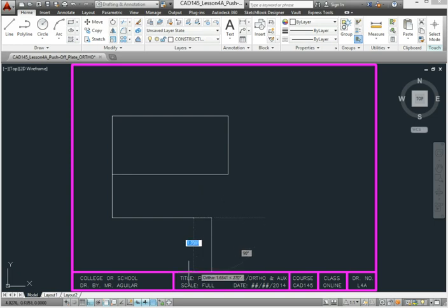This is where ortho will switch to polar tracking. You would move your mouse until the angle reaches a 45-degree angle line, which would be highlighted with a green dashed reference of 45 degrees. That's called polar tracking. Once we get that direction of 45 degrees, you could type in the distance of 2 1/16. If you notice you're too close to the border, we can move later. That'd be 1/2.